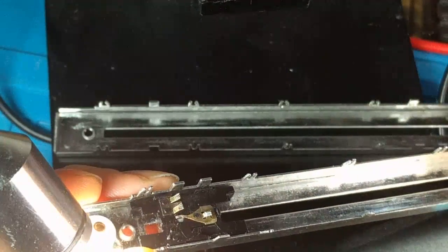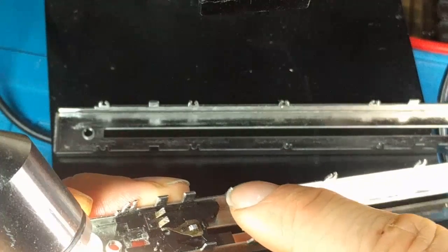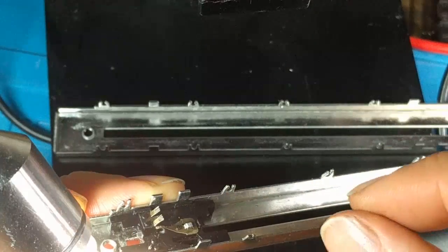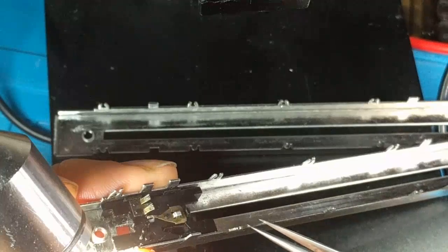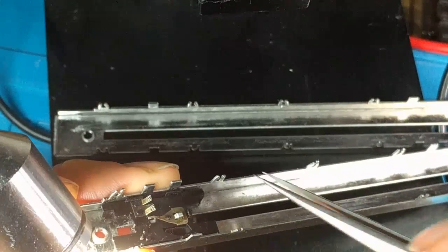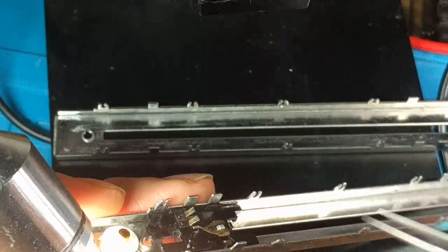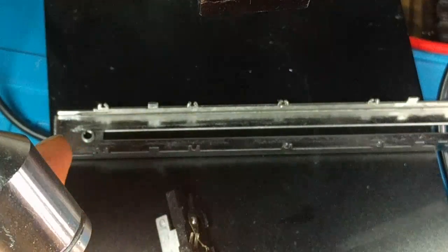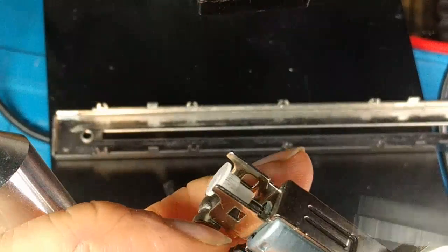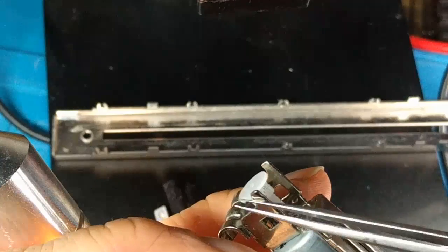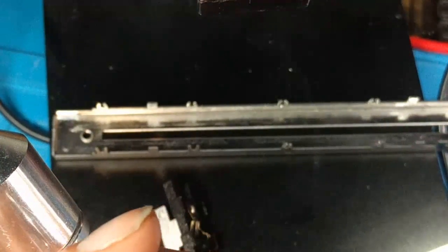And yeah, what you'll do is bend together these little metal tabs. You bend them together, the gap between them, and then maybe you can gently push out if you need to, and then the two pieces will come apart and the board will come out. There's a plastic cap over the motor bit. There's a black plastic cap here normally, which holds the belt in place, so you can actually just angle it outwards and you don't have to undo all that.